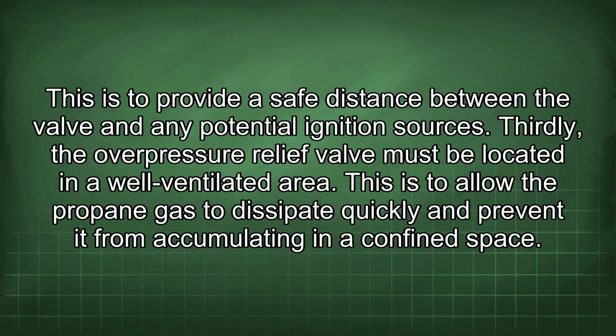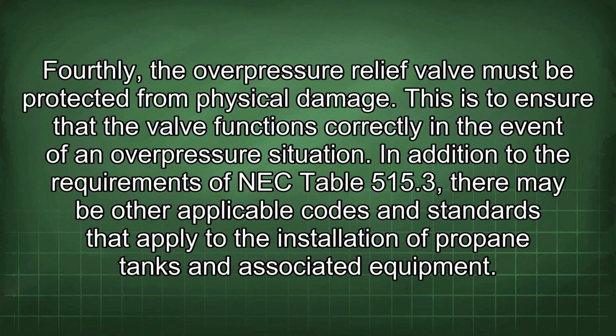Thirdly, the overpressure relief valve must be located in a well-ventilated area. This is to allow the propane gas to dissipate quickly and prevent it from accumulating in a confined space. Fourthly, the overpressure relief valve must be protected from physical damage. This is to ensure that the valve functions correctly in the event of an overpressure situation.